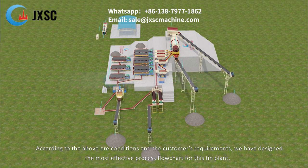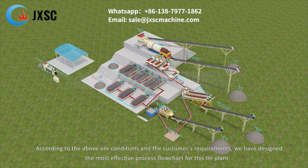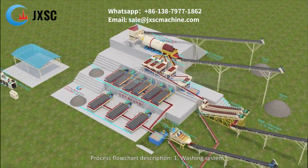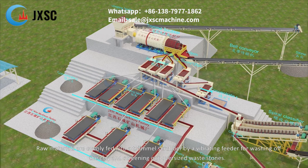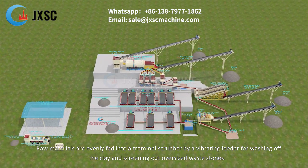According to the above ore conditions and the customer's requirements, we have designed the most effective process flowchart for this tin plant. Process flowchart description. 1. Washing system. Raw materials are evenly fed into a trommel scrubber by a vibrating feeder for washing off the clay and screening out oversized waste stones.